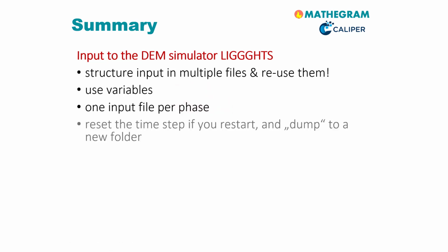If you look closer into the second input script for emptying, you will see that we have reset the time step after the restart command. And this is important because the dump files are numbered according to the time steps. Also, it is important that we always dump our snapshots to a new folder.